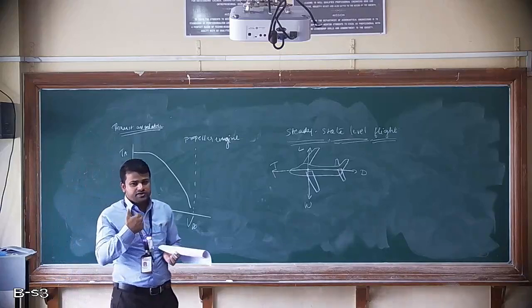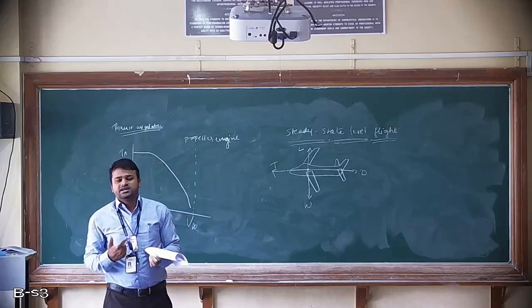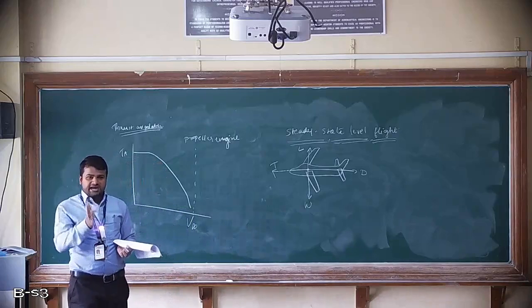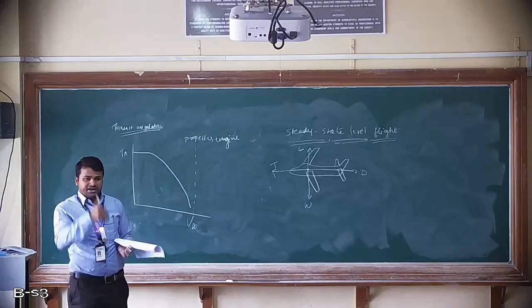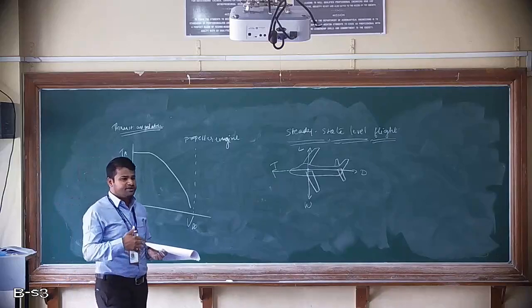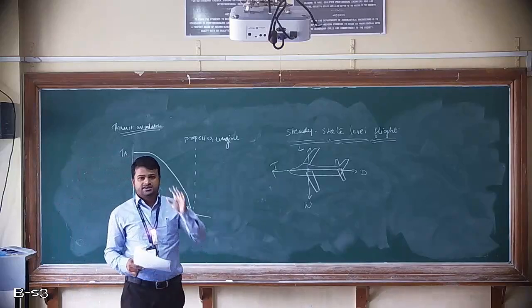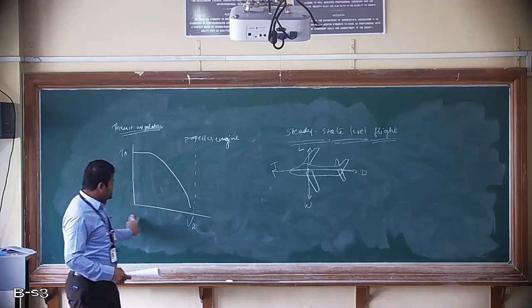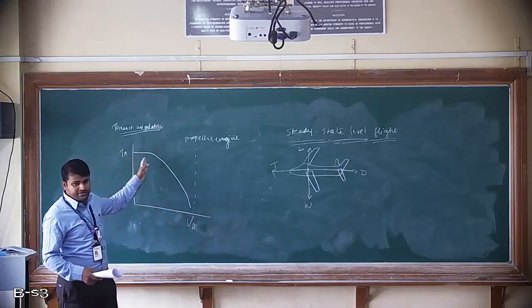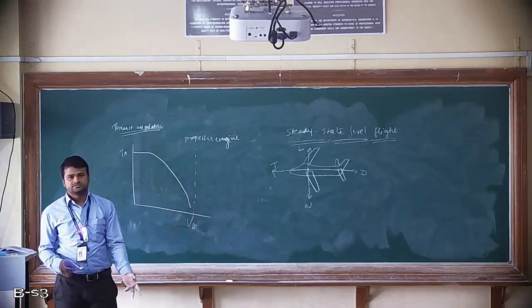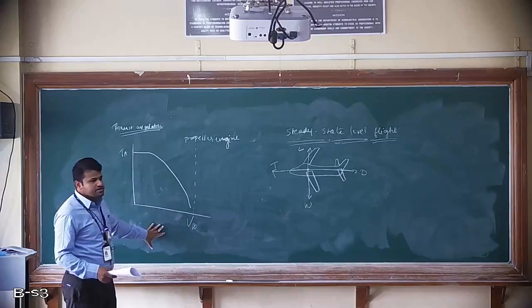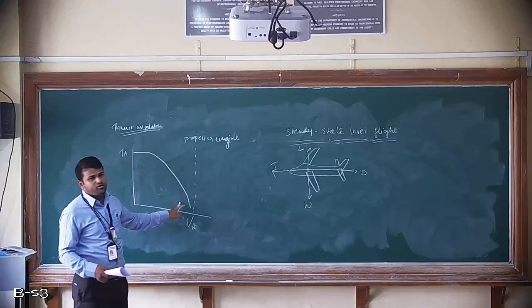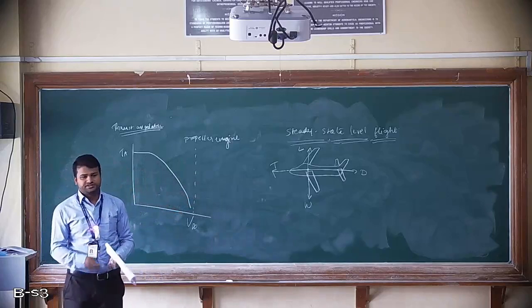But as speed increases, what will happen? Let us say it is about to reach the sonic condition, Mach number 1. It will start experiencing the compressibility effect. That means stalling starts happening, which in turn reduces the thrust. Instead of giving more thrust, the thrust starts to reduce. The propellers are designed in such a way that at higher airspeed the thrust available will reduce. So this is the thrust available curve for a propeller engine, and this is happening because of the compressibility effect.